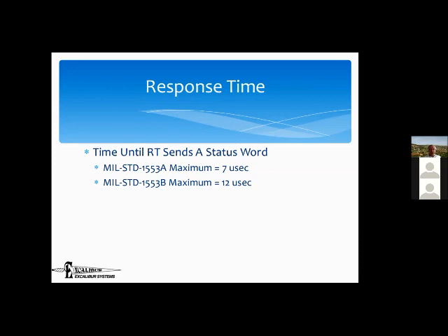Now, the RT's time doesn't start when the bus controller transmits the command word. It starts when the RT gets the command word. And then he has his 12 microseconds. But then when he sends his status word, it takes time till it gets to the bus controller. So that adds more delay. So the bus controller wants to allow more than 12. Typically, they'll allow like 14, 15 microseconds.